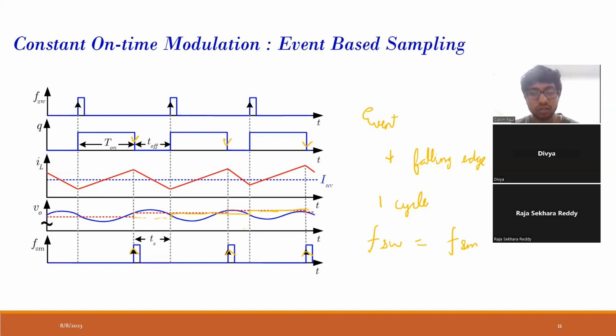So one more thing to know is you don't know exactly when it will finish converting. It might finish converting over here, or it might finish converting over here. The ADC might take only this much duration to convert, or it might take this much duration. But we take the worst case scenario, and we decide the ADC for an application. And we will tell in our control logic that only after this delay TS do you update this value.